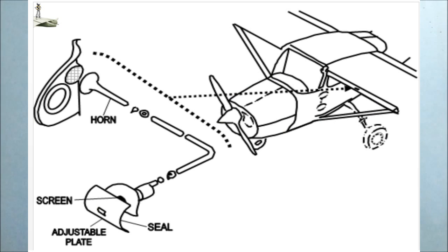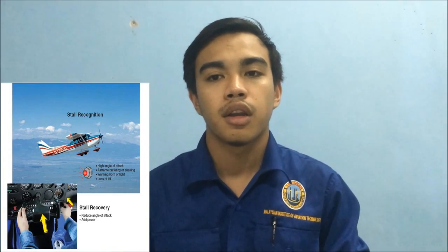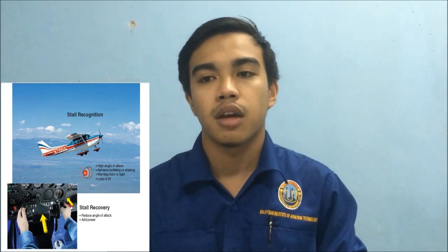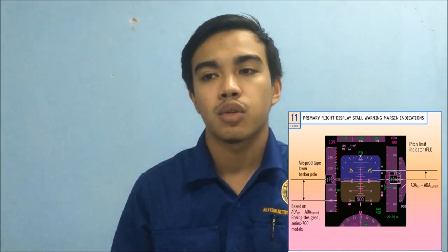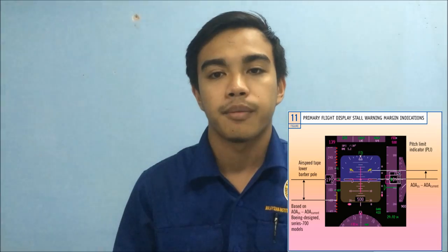The system works as follows. The plenum chamber is connected by tube to a horn assembly in the cabin. As the angle of attack is increased, the slot is so positioned that it reaches a low pressure area sufficient to draw air through the horn assembly, which will emit a noise and alert the pilot to an impending stall.